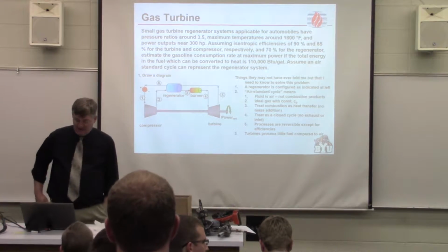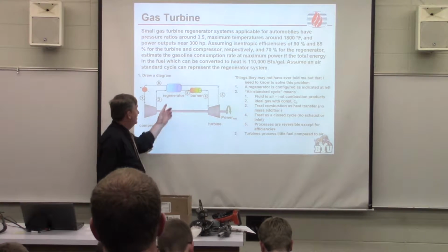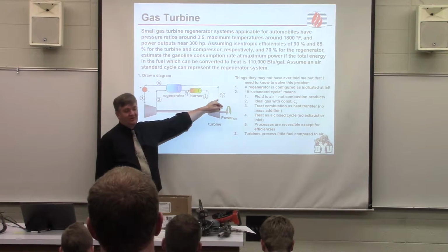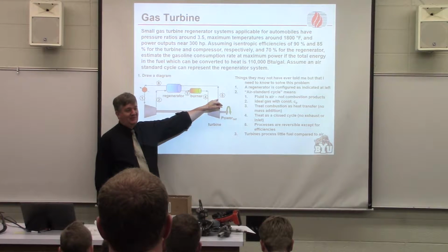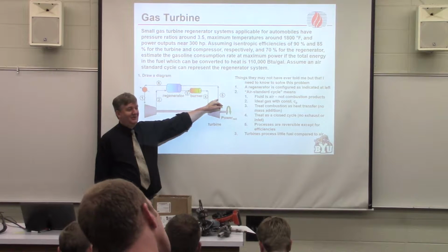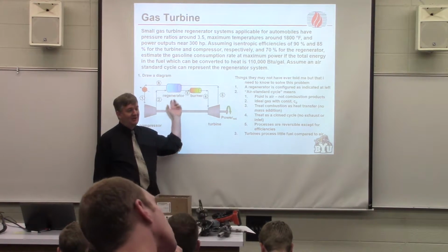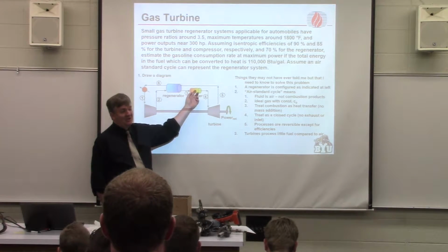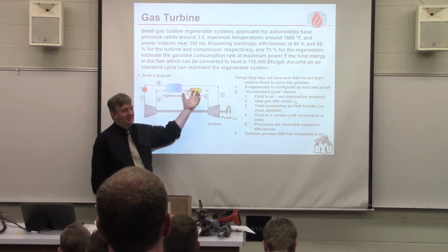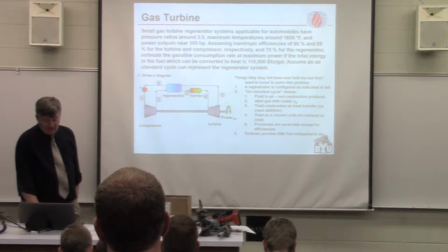I'll show you in just a minute how this can make the analysis pretty simple. First of all, if you calculate the amount of fuel that goes in here, the mass of material in this stream that originates as fuel for a typical turbine engine is like 3%. So the fact that you're adding fuel here is a relatively small perturbation on the other analysis. You can't ignore the energy that you have here, but if you just say we're going to heat this up and pretend we just heated it up with no fuel, then that's a pretty close approximation to what happened.